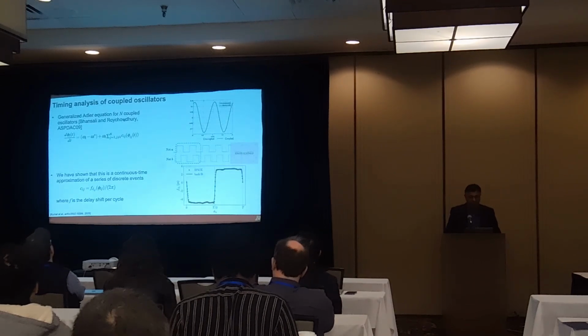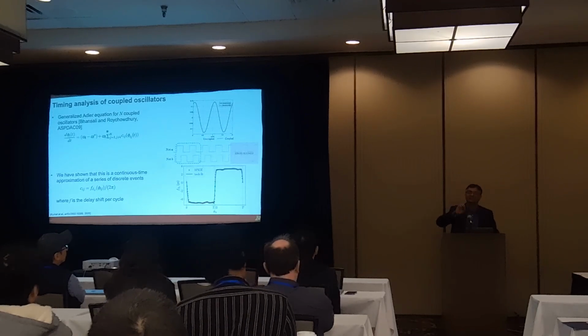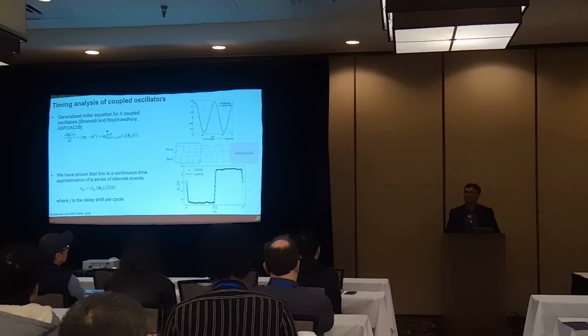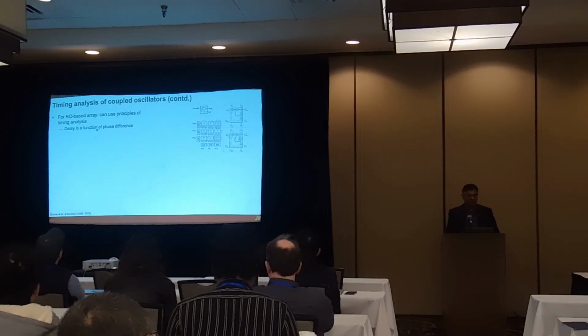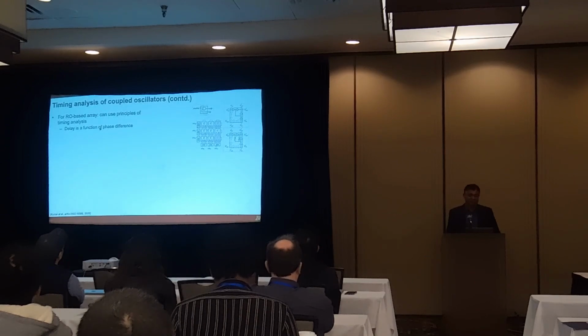So when this was done, these guys are SPICE simulation type of guys. I'm a timing analysis kind of guy. And so when I saw ring oscillators over here, I said, well, you don't really need to do all this. You can actually think about it as timing analysis. You have delays going through stages. You can think about these as discrete events. And you can actually use the principles of timing analysis to get pretty much the same thing, and get it more accurately, because there are subtle effects that the continuous function doesn't capture. So the delay can be captured as a function of phase difference.